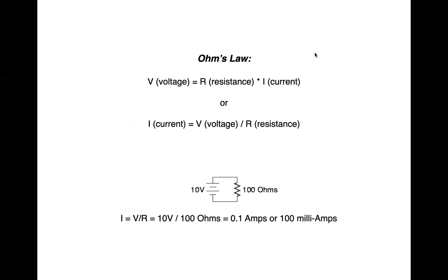One of the most fundamental laws in circuits is Ohm's law. That means that the current flowing through the circuit times the component's impedance, in this case resistance, equals the voltage consumed. For example, there's a very simple example here. A 10-volt voltage source is providing current to this circuit, and the circuit only consists of 100 ohms resistance.